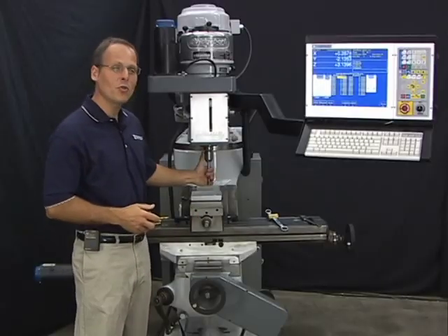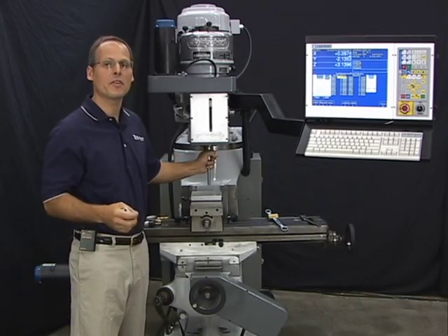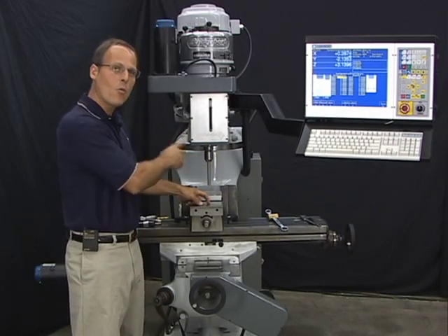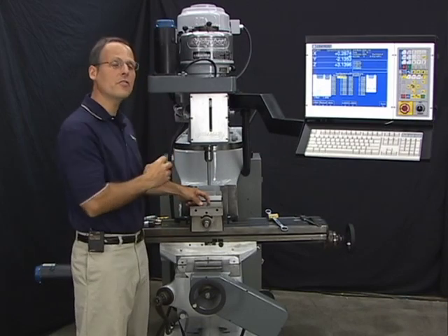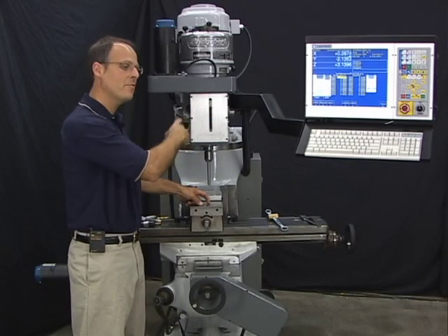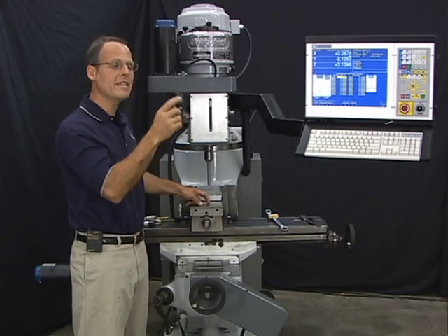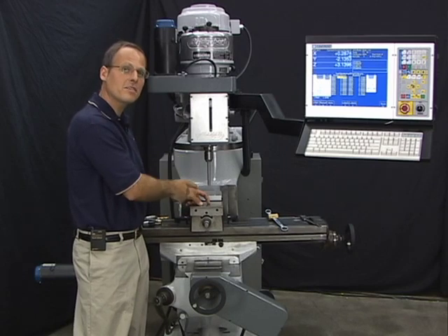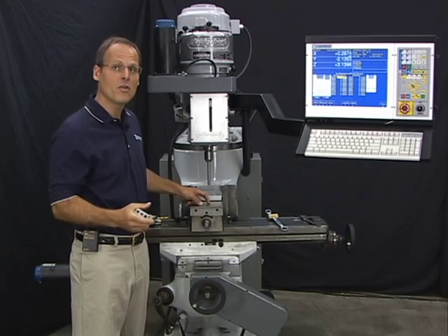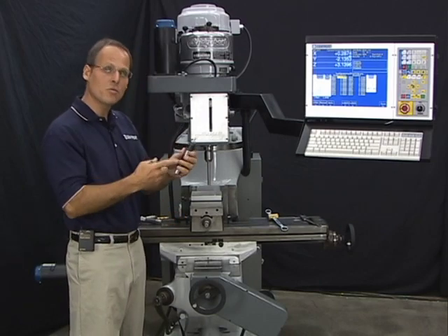Okay, I got my reference tool loaded up in the spindle. Let me explain how we're going to use the reference tool to measure the difference in length between all the other tools. What we're going to do is jog it down to a position and have the control remember where that reference tool is. Then we'll load up another tool, jog down and touch that same position. Now it's going to take an additional amount of movement for the control to get that shorter tool to that same position. The control then knows the extra distance that tool had to move to touch the same spot that we used to touch with the reference tool. That is the height offset value. That is simply the difference in length between the reference tool and my tools.